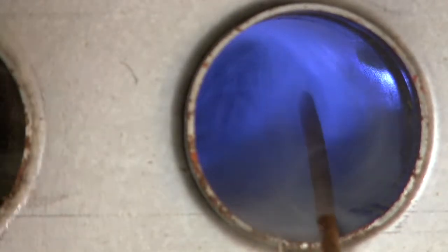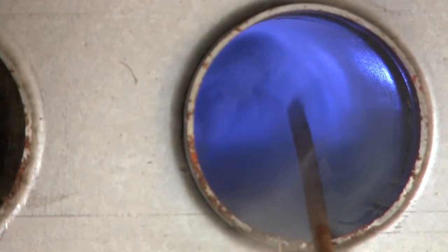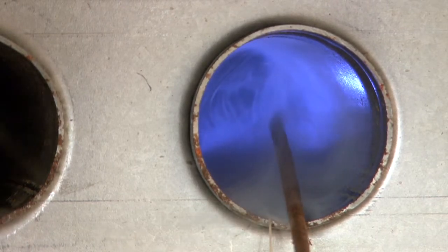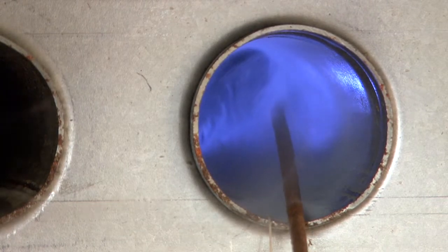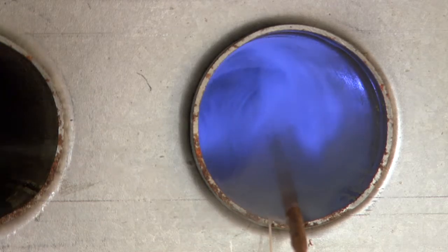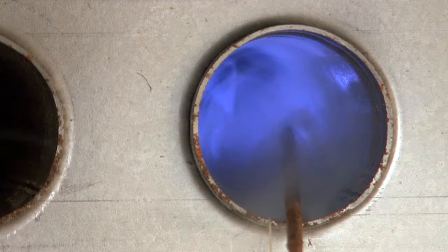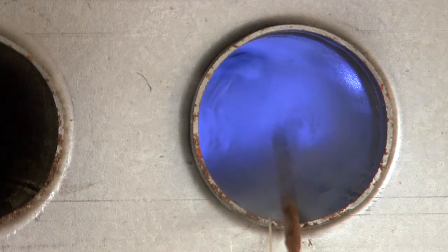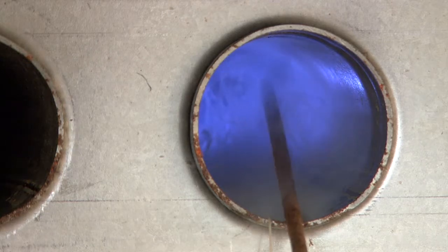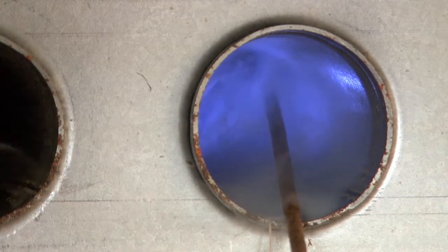So then what you would do at that point is hook the inducer back up and run just the inducer, giving it a call for heat. Obviously you've got the burner assembly and everything off of here, so there's no way it can light. Then we can just take the incense stick and put the smoke up in front of each cell and make sure each cell's drawing evenly, because it should be. So I just thought I'd point that out as another possible test you could be doing here.